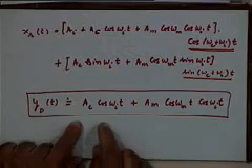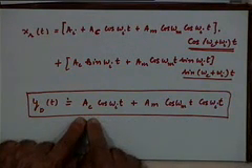First conclusion from this discussion is that the envelope detector now thinks that the carrier is not omega c, but omega c plus omega I. So in a way, the stronger of the two components captures the envelope detector output. If the interfering component is stronger, it captures the receiver. It will dictate what the output of the envelope detector would be, rather than allowing the carrier component to dictate. And once it dictates that, the output has no resemblance to the message signal.